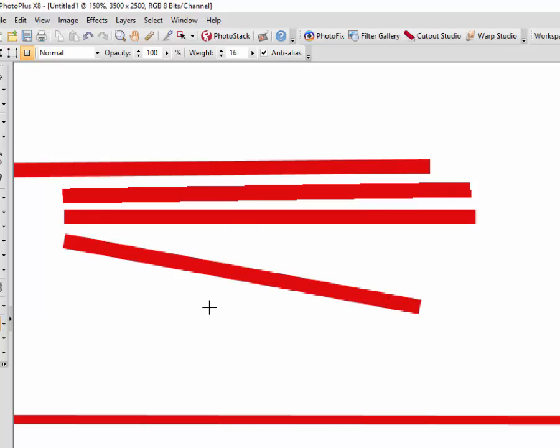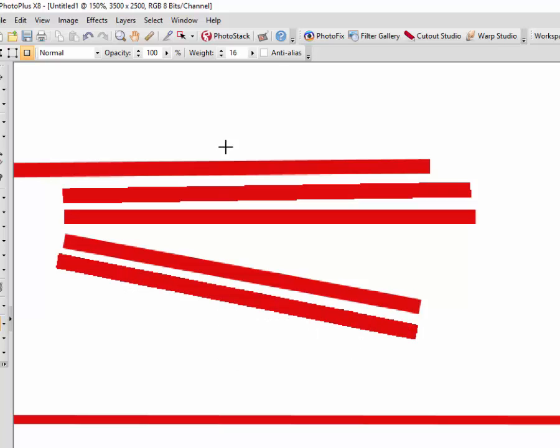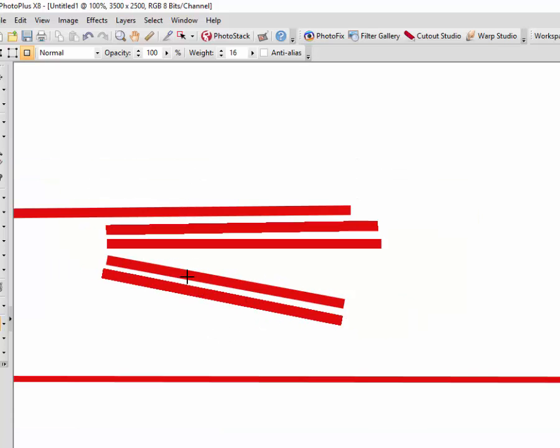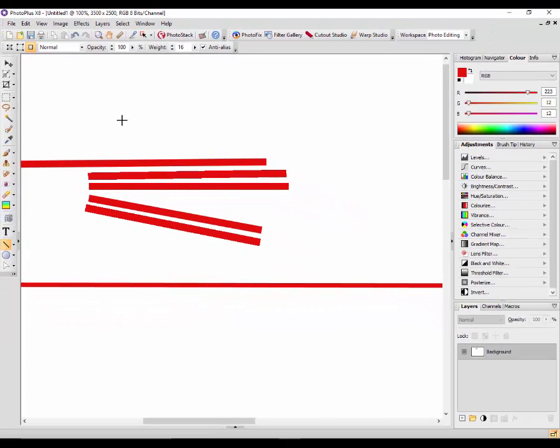It's when you come down at an angle, as you can see that, I mean, obviously that does have jagged edges, but it's even more pronounced when I untick the anti-alias. And as this is zoomed in to, was it 150%, that is more noticeable. If I zoom out to 100%, that one looks smoother, and that one looks all jagged. So I would imagine that most of the time you will want anti-alias ticked, so you have nice smooth edges. I'll just lower this back down to 10.